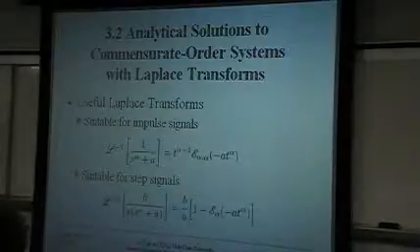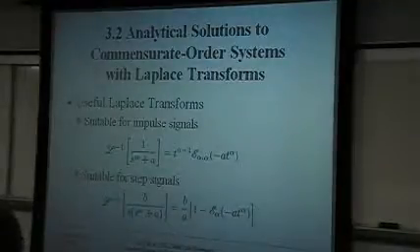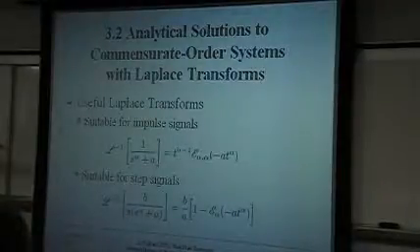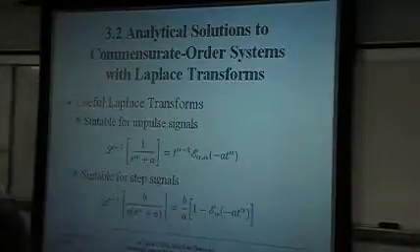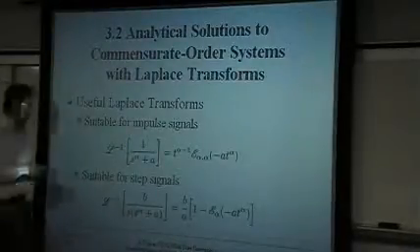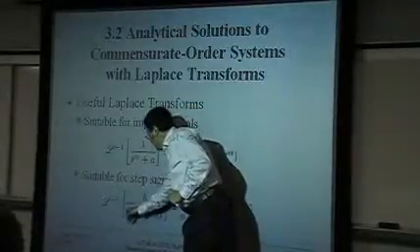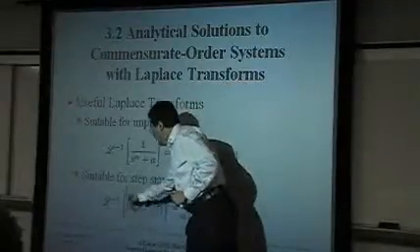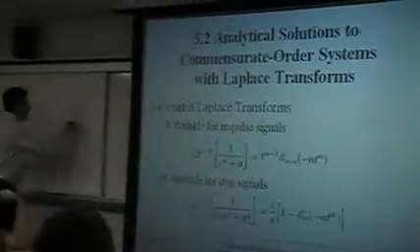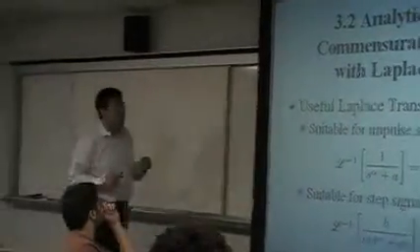For the system, we can redefine it using what is called a partial fraction expansion, and find the other terms like this, then we can find the analytical solution for the whole system. I will explain that one later. And there is another important property defined like this, where there is 1/s in the system, and we can see that this part can be considered as the step response of the system, like this. So we can make use of the two terms.